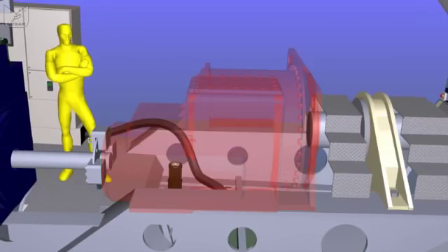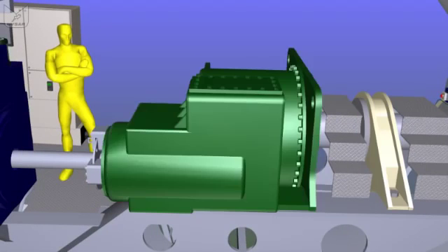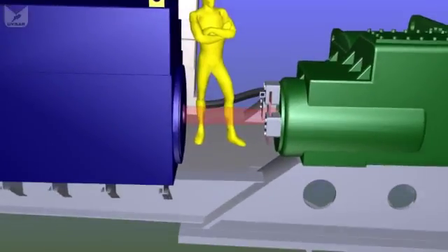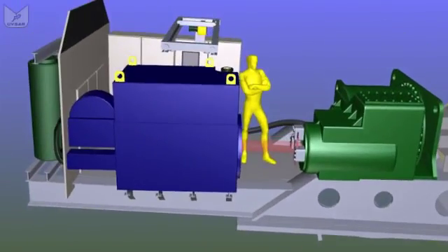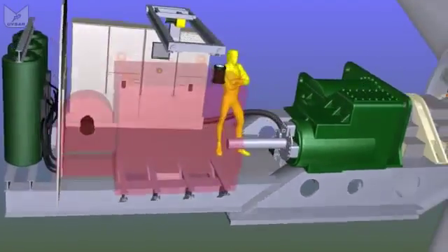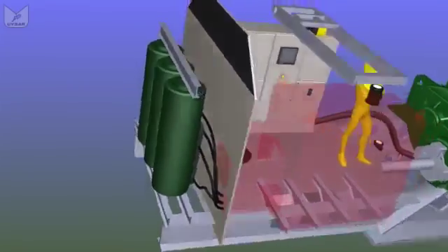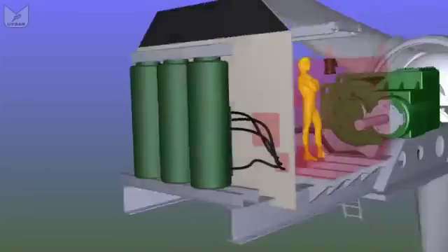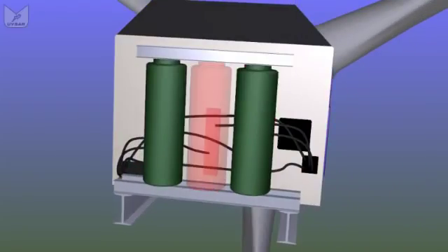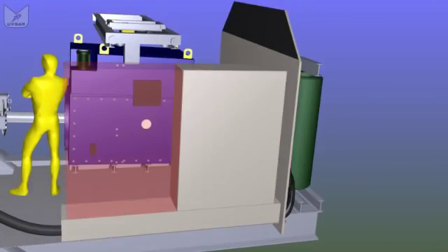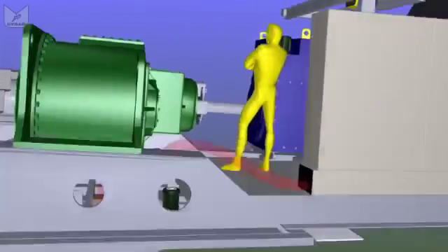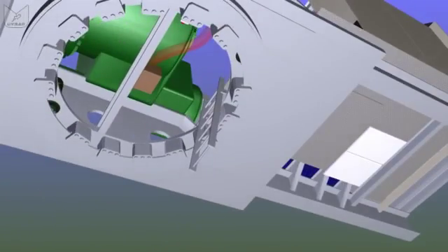So our main shaft drives our gearbox, which is mounted centrally because it's often the heaviest component. Out of the back comes a high-speed shaft, as before. That's where the braking system is. The high-speed shaft then drives the generator, which is usually oil-filled. The generator then supplies 690 volts, in this case into our transformer, which is sitting right next to it. That high-voltage signal then passes through the switchgear and the cabinets, down the dropper cable, straight down to the bottom of the tower, through those switches on platform 2 and off to the substation.